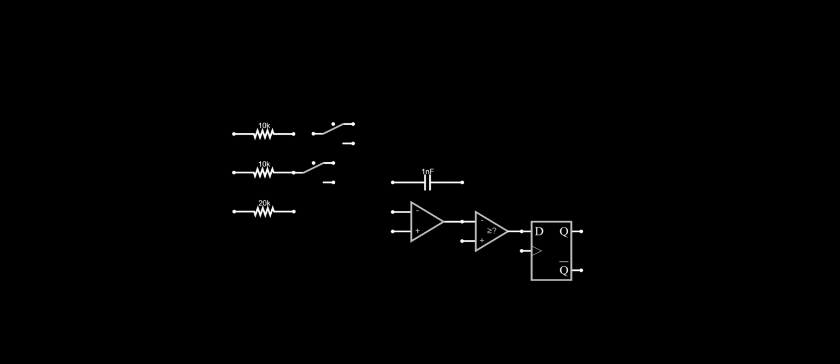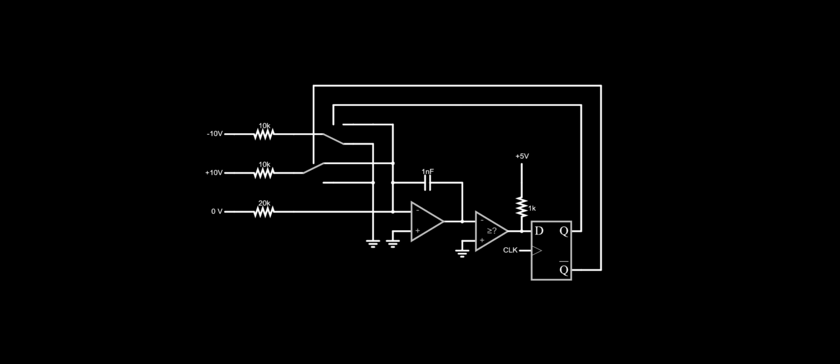An operational amplifier, a good capacitor, analog switches, a resistor network, a comparator, and some logic. These simple ingredients, when put together, result in an ADC that is much greater than the sum of its parts. The multislope ADC is a charge balancing topology.